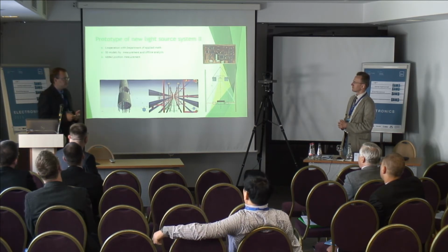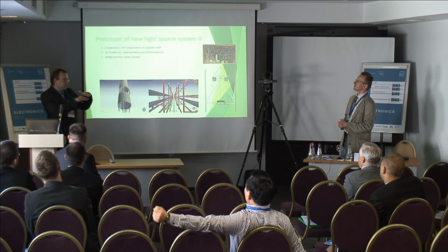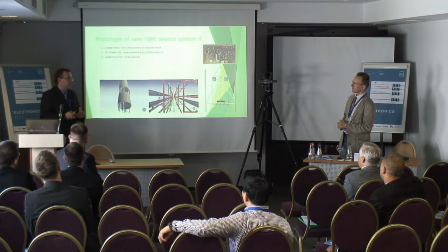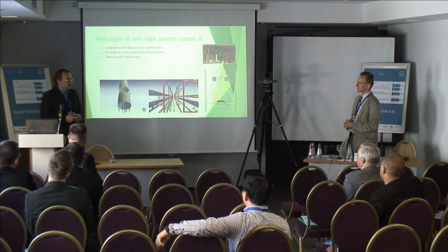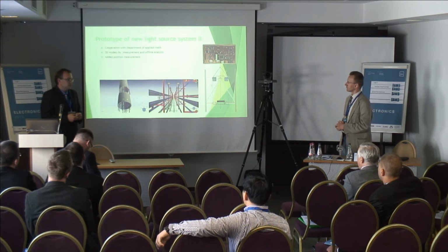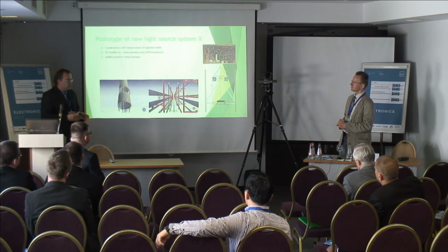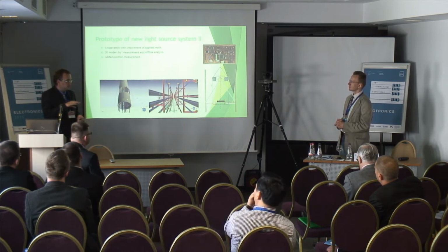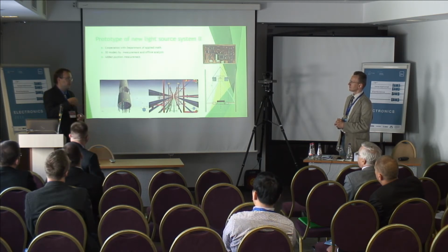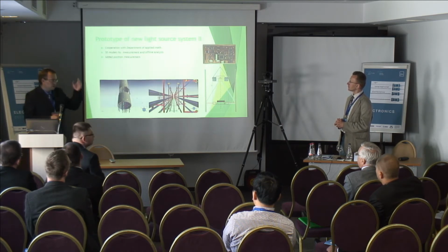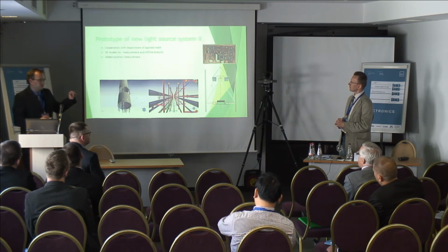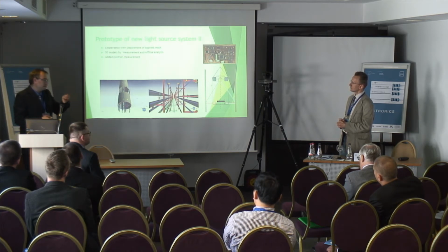Vertical resolution is not per millimeters. It's approximately on the order of tens of centimeters, up to 2 meters. The problem is that it's mounted on the mine lift, which limits the speed of the movement. Because if you stop it, it's not good for the measurement, because it adds more errors. We compute horizontal and vertical position from the lift. We can add another pressure sensor and so on, but today we use this position.